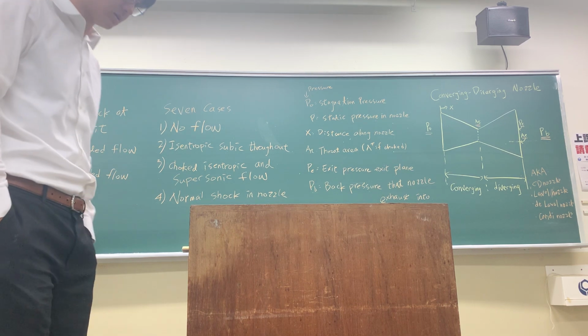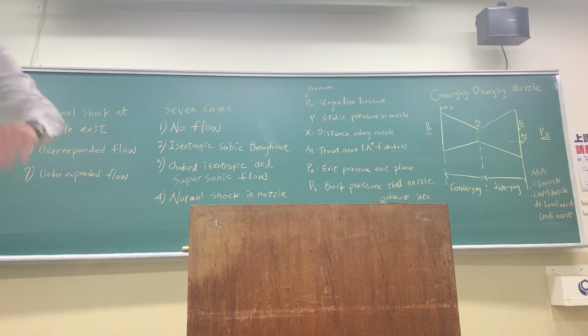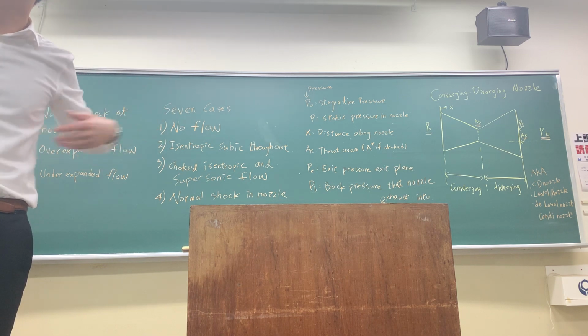So, while you guys are writing down, I'll give you every case you can come up with for your design, convergent-divergent also. What you're seeing right now is a convergent-divergent nozzle, meaning on the left-hand side is the convergent, and on the other side is the divergent. When you design, there's always at the middle the A_T. A means the area, T means the throat, the neck. So P naught means the stagnation pressure. You can think about that as the reservoir, the combustion chamber.